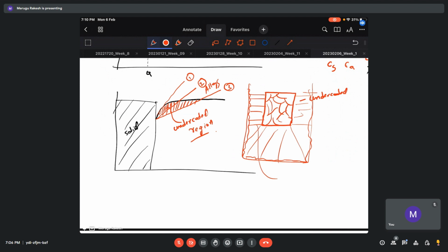And these columnar structures also will not be columnar, they will be dendritic because of this solute rejection or inhomogeneous distribution. This is in dendrites in general, in these alloys. So say this is the dendritic structure. A dendritic structure is nothing but the root structure of a tree. If you see the roots of a tree, or any coriander leaves, you can see that structure, right? A big branch root is coming, then followed by the small branches.